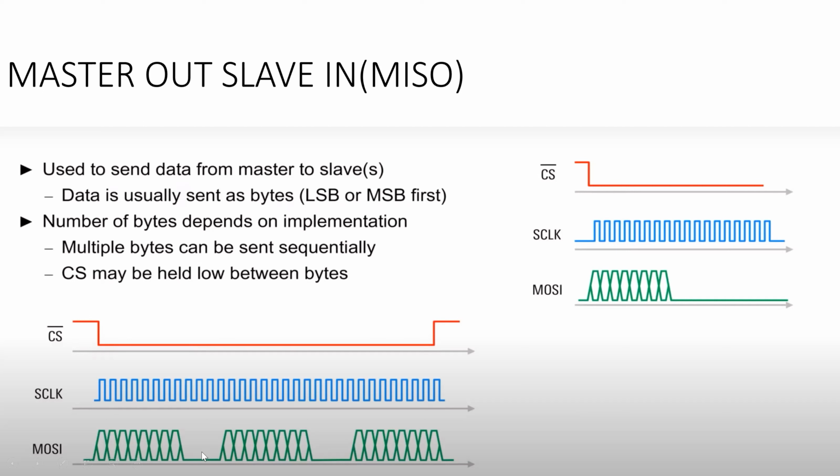You can see here, this is the first bit it will be transferring to the receiver, and the second bit will start at this point. So between these 2 bytes, in this duration of time, the chip select will be held low, right? Can you see? I hope you are seeing.